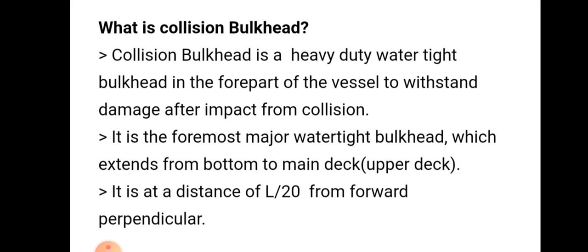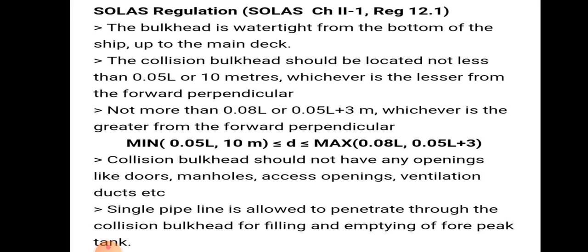It is the foremost major watertight bulkhead, which extends from the bottom to the main deck or upper deck. It is at a distance of L/20 from the forward perpendicular. SOLAS regulation, that means SOLAS Chapter 2 Regulation 12.1: the bulkhead is watertight from the bottom of the ship up to the main deck.